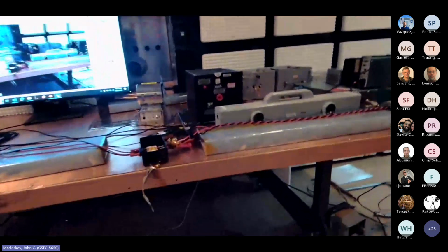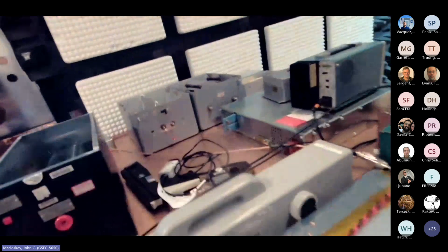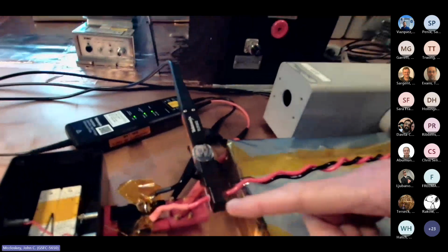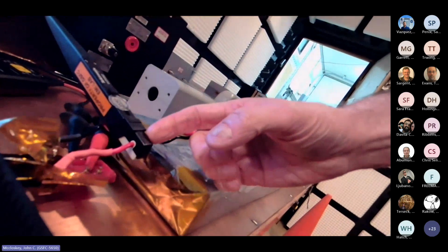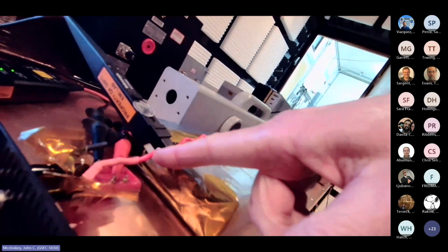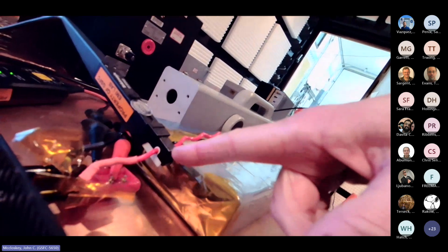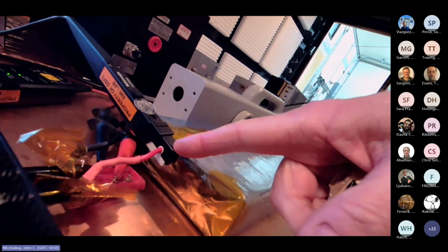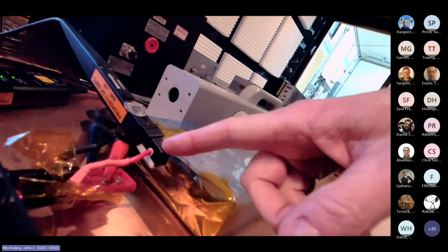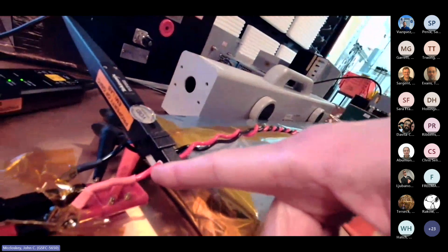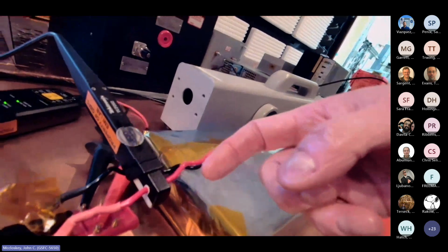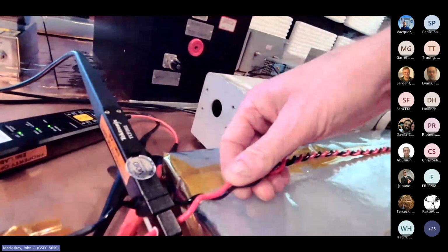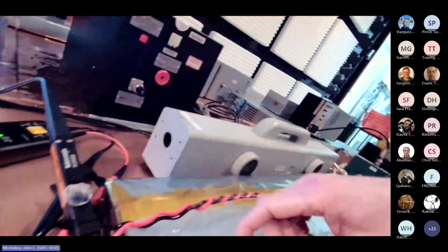So in the time domain, that means an oscilloscope by and large. And this current probe here is a pretty standard current probe used with a scope. Well, it's got a very small aperture. It's meant to basically look at one wire at a time, or maybe you might have a small group of small wires. We've done that. But this is about the largest wire you can fit through that aperture. So to look at common mode, even just on this pair of wires, can't use this probe.